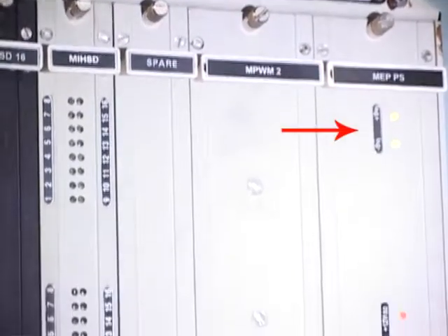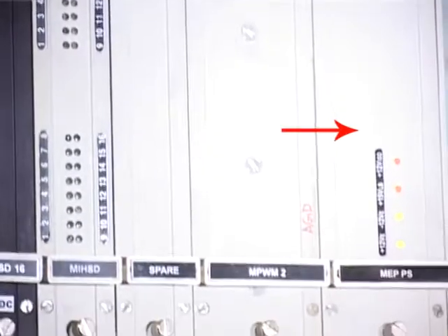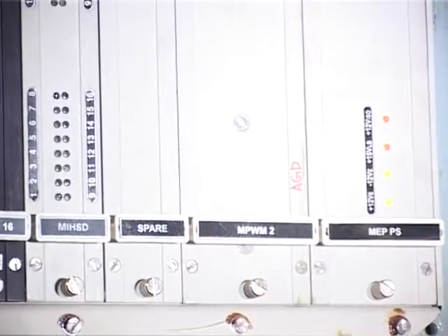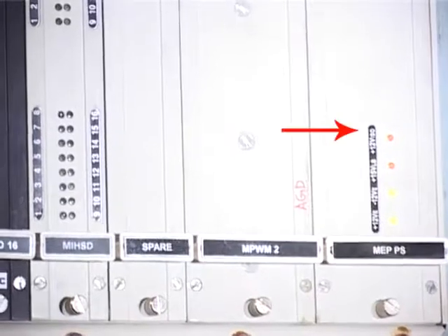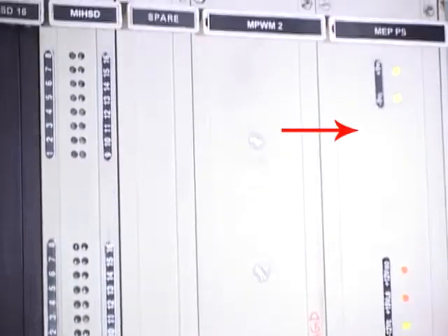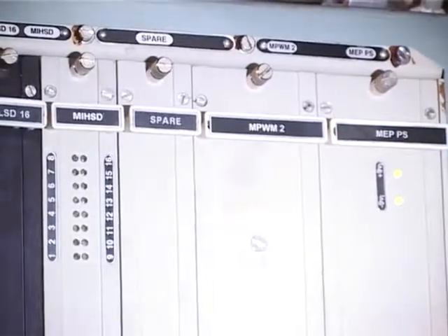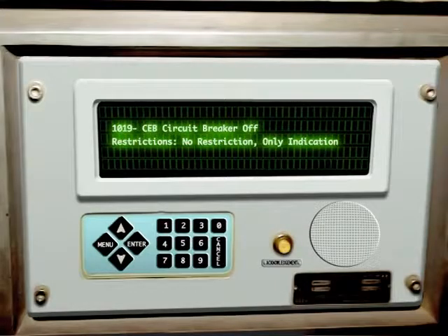Excitation and propulsion power supply card MEPPS. This module supplies various regulated power supplies of ±9 volt, ±12 volt and ±15 volt required for the operation of all the cards in the control unit. Display unit. This sub-assembly consists of a 40-character X 4 line alphanumeric vacuum fluorescent display, VFD. It also consists of a keyboard for data entry by the operator and an acknowledge switch to silence the built-in buzzer, hooter and alarm gong ALG during fault message display.